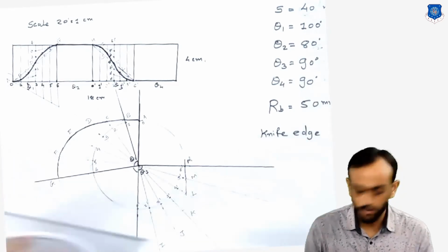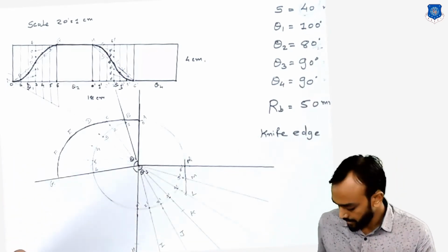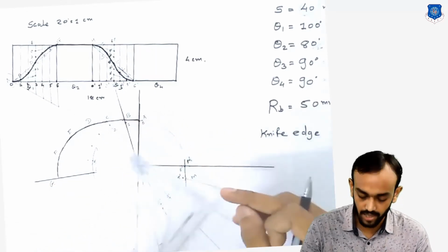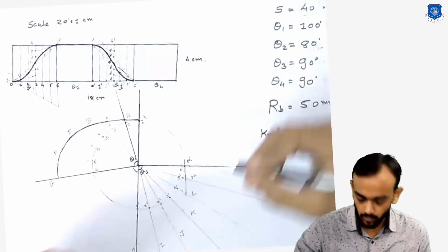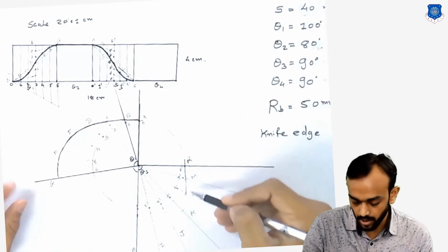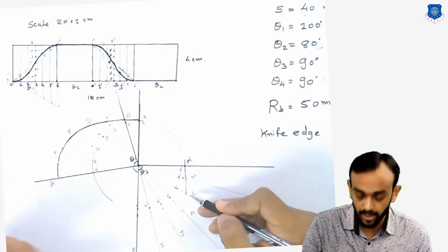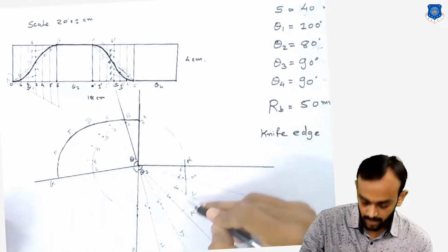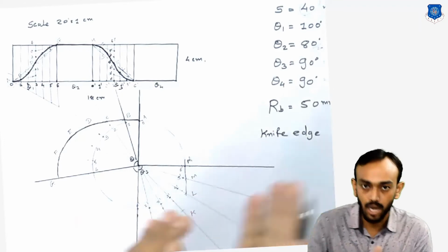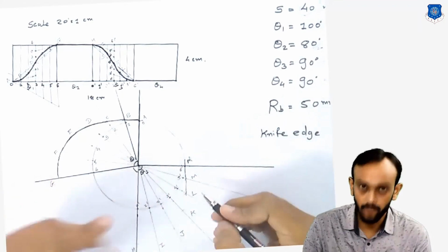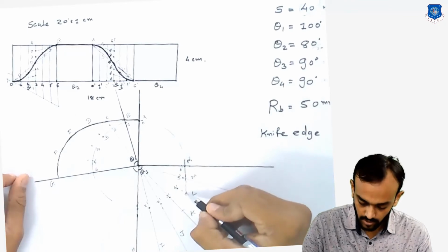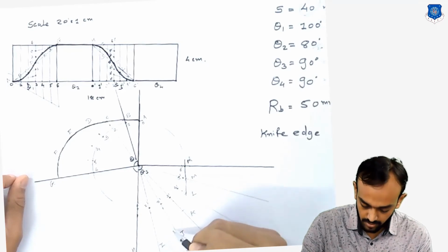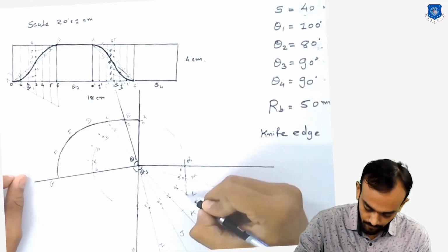While drawing this curve, you can use the French curve. Using it you can connect the points as smoothly as possible. Whenever you draw this curve, remember that we are drawing this line from these two points, but after 2 or 3 points you also have to figure out how the curve will go. Draw very carefully and smoothly. So if I am drawing the line here, first of all I will see this point and this point, so this curve will be something like this.